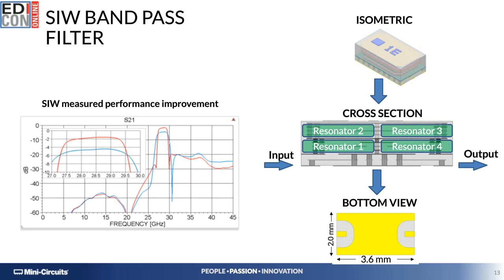We see very high mid-band insertion losses with respect to a second spin on the same, employing the advanced technological materials which are composed of improved powders on the LTCC side, as well as conductive pastes on the conductor side.